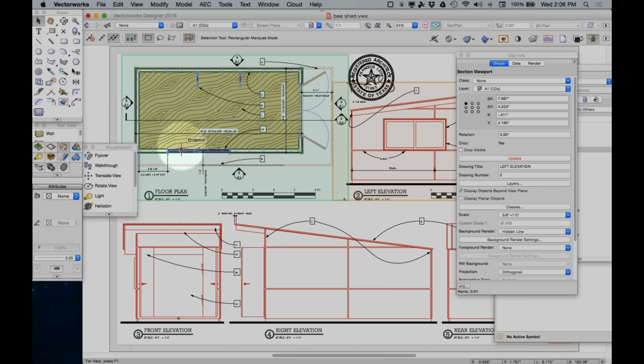Okay, I have one more question if you have a few seconds. Sure. Why use a floor and not a slab? I could have done it as a slab. I chose to do it as a floor because it was just quick and easy. Okay. If it was a concrete slab with perimeter and interior grade beams, I would have modeled it as a slab object and then subtracted out those voids.